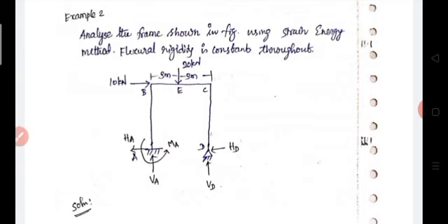The energy method is a force method, so that means we have to select the force as an unknown. In the force method, forces are treated as unknowns. These forces are determined with the help of compatibility equations. In addition to equilibrium equations, we use compatibility equations. With both, we determine the support reactions. Then finally we draw the shear force and bending moment diagrams.